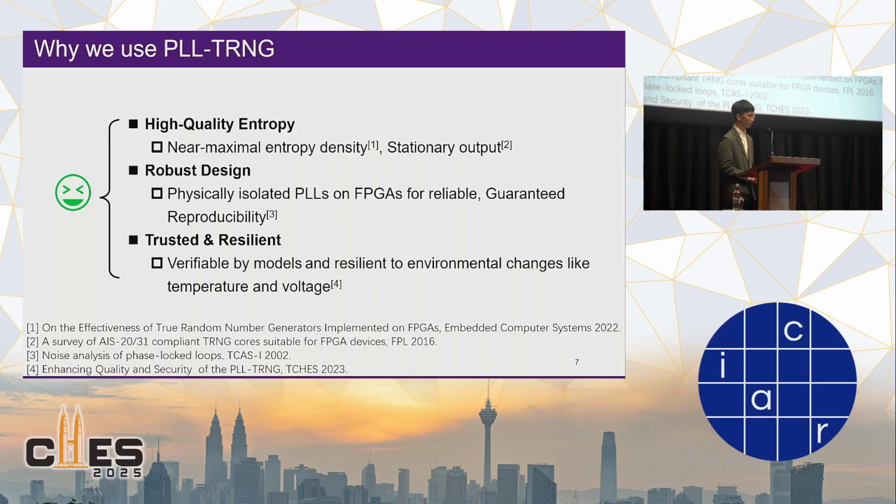A PLL is excellent at delivering the randomness into the digital bit, which means the raw output of the digital noise source can be used directly without any extra post-processing. And besides, once the PLL is locked, the jitter of the PLL is known as a stationary process, which is an advantage for reliability.